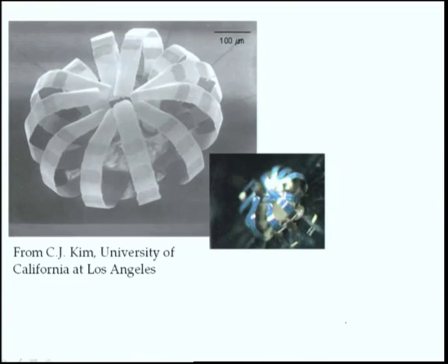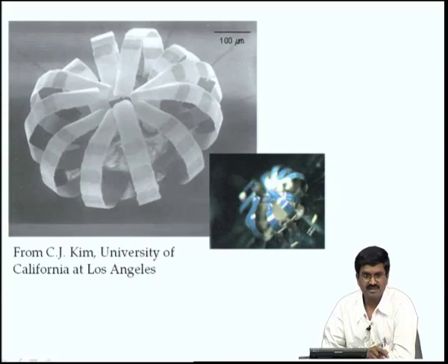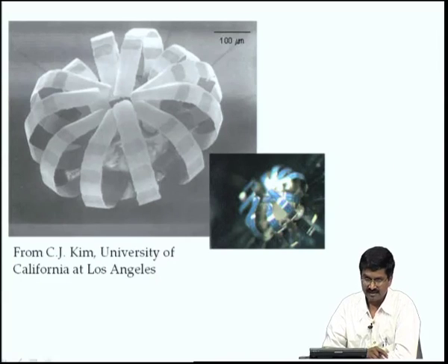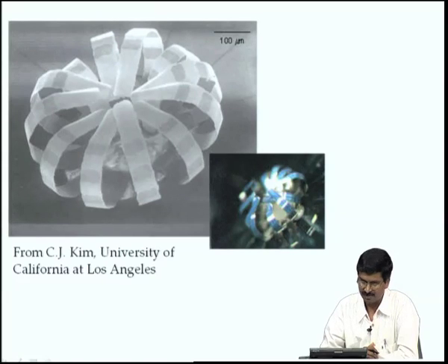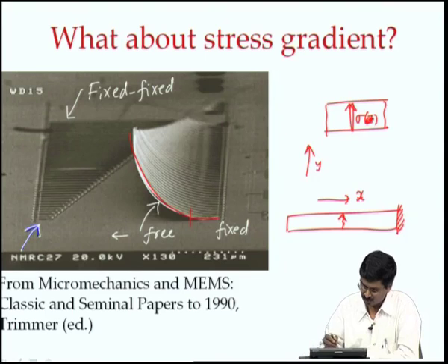Okay. So, now we discussed the effect of residual stress and stress gradient. What are the applications of it? It is a bad effect in the sense that it will have some unknown stress which is quite difficult to measure. When you have in a laboratory process some micro machine structure, assessing how much residual stress there is in it at the end of the processing, when you package and ship the chips, it is difficult to assess. There are methods, expensive equipment is needed in order to measure this residual stress, but what can be done is to throw in a few cantilever beams such as these and see how much they rotate.